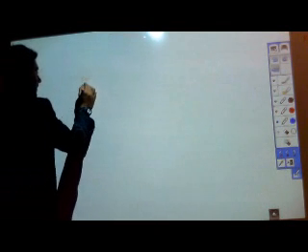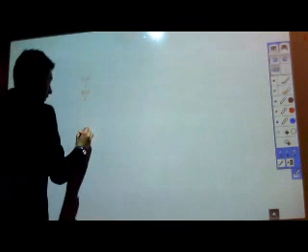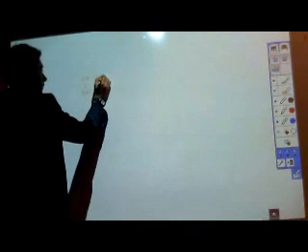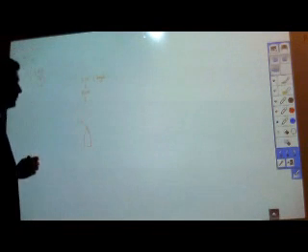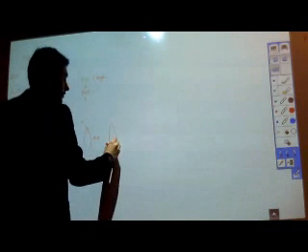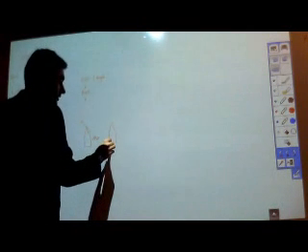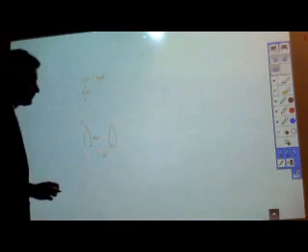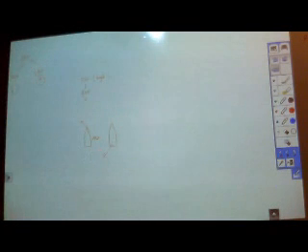So the rule of thumb is what you came to a conclusion. Let's talk about the fixed pitch right-handed propeller. When the vessel is going ahead, and we are talking about a single propeller at the moment, it is going to turn to port. And when the vessel is going to come astern, the stern is going to come to port.